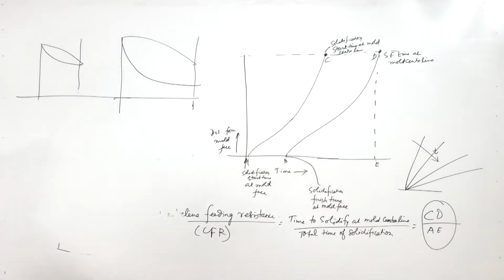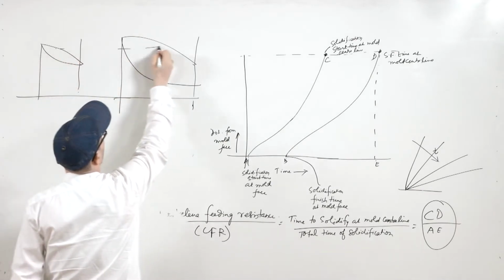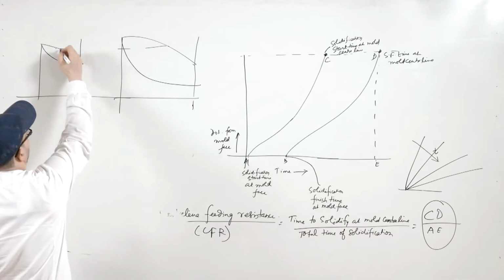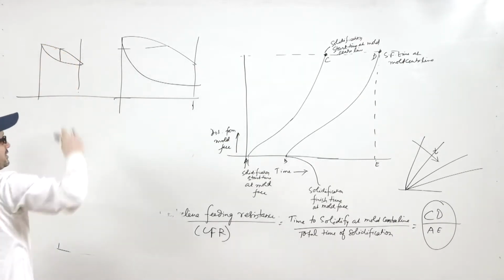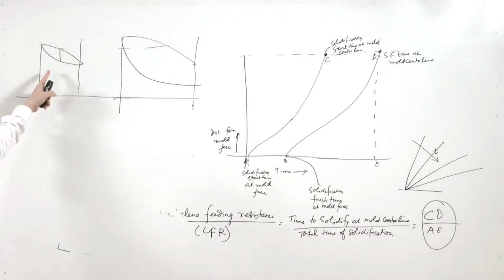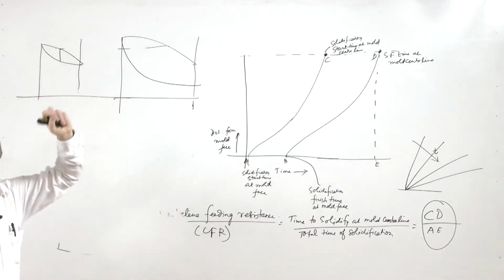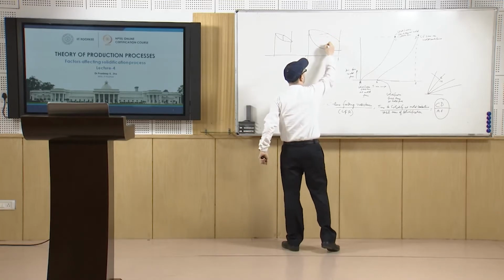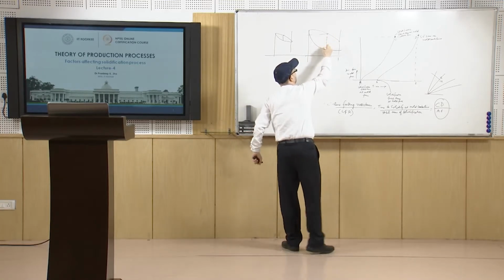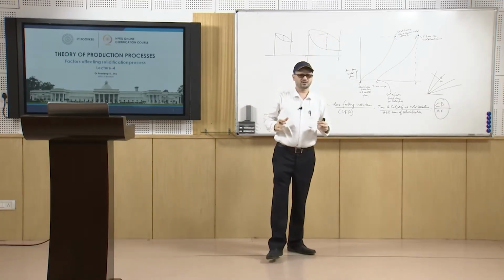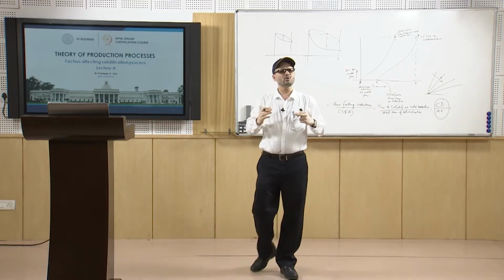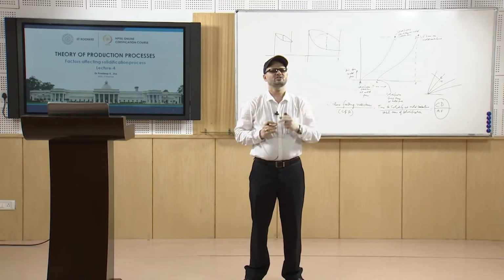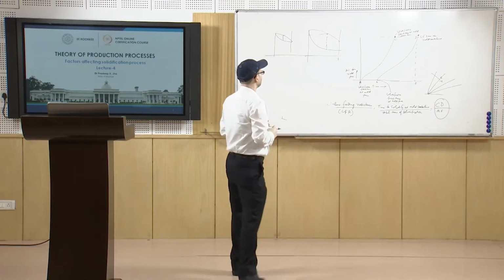Now, in this case the solidification starts maybe at the same temperature, but in this case it can be said that as soon as it reaches here the solidification is complete, whereas here it has to traverse a long distance, and after a lot of time it takes to finish, and the situation becomes more and more severe towards the central part of the casting, the center line of the casting.